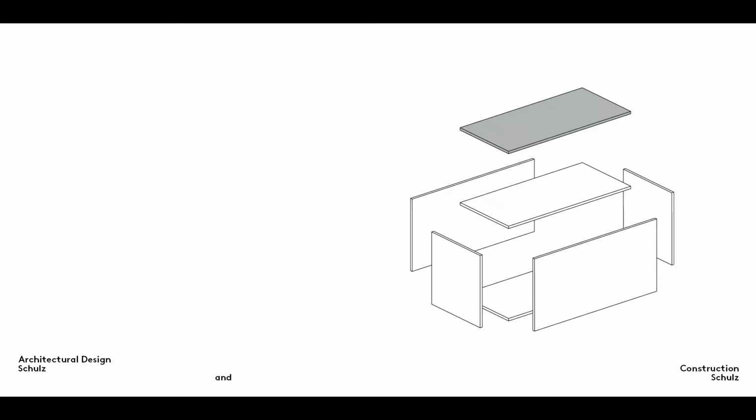Since it forms part of the building shell, however, it is subject to stricter requirements in terms of protection against the weather, durability, heat insulation, and many other factors. Like a flat roof, a pitched roof may simply be a flat element that has been tilted in relation to the horizontal. In practice, however, this is far more complex than it sounds, for the time and effort required to construct a pitched solid slab of reinforced concrete, for example, is far greater than that for a flat slab.